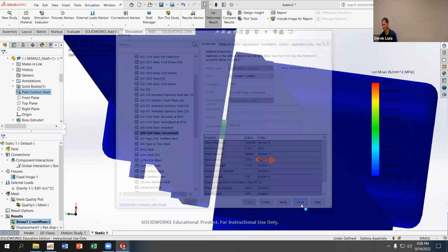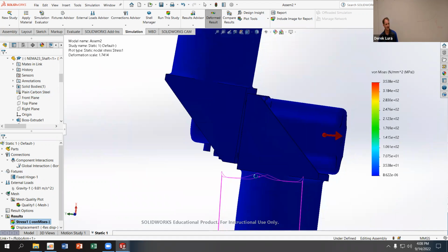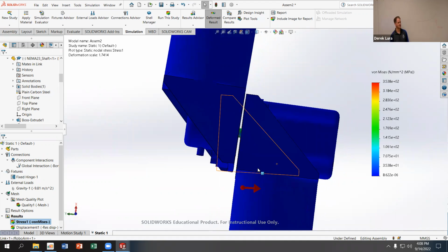And in this case, I've not designed this very well because I have no bearings to support the loads and distribute them inside this robot. I don't know why, but I see that a lot in robots where the mechanical coupling is basically being held by the motor as opposed to something that's going to distribute the force over a large area and then attaching the motor to that. I think they're just trying to save space and weight.